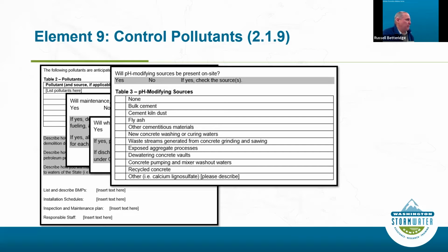If you're going to start amending your soils with fly ash, that's a really specific construction technique that you need to control. What happens if it starts raining while you're in the middle of amending those soils to make them hold up your building?